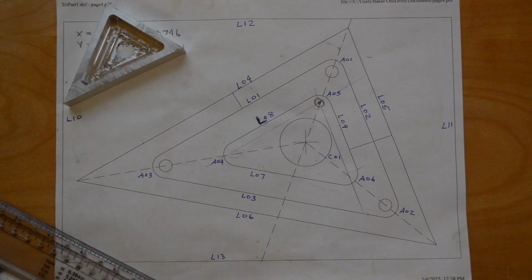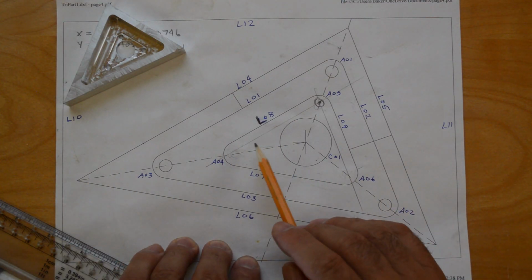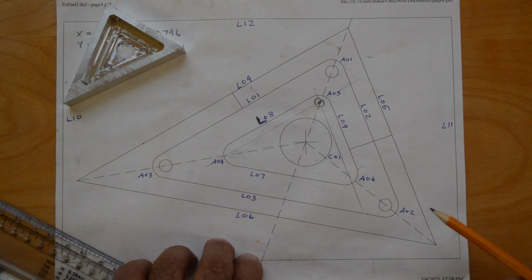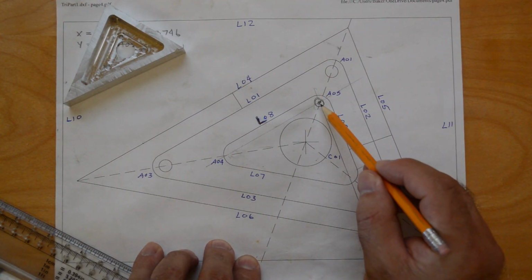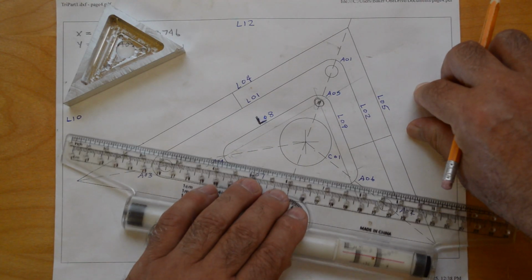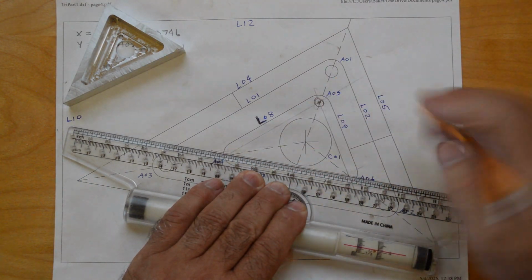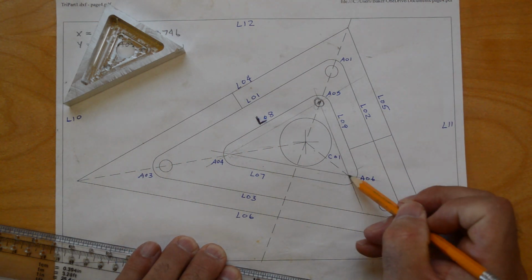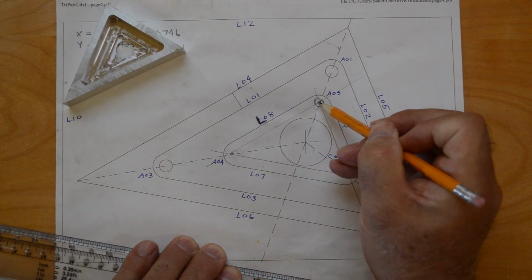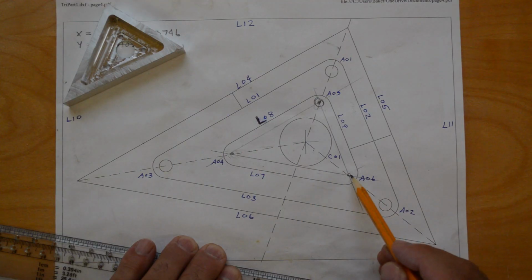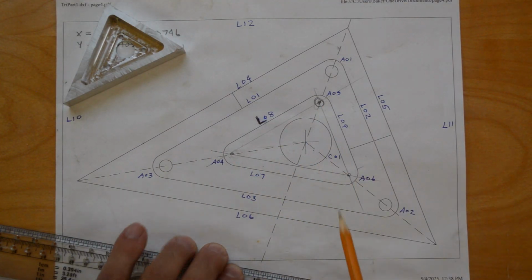So that's what we're going to do on the Cartesian display now. We're going to define these lines, and they are going to become part of our part model. I will be able to use them on radar to navigate to these points and drill these holes. We'll define 3 lines actually, at a 0.125 offset from each one of these walls. So I'll have a point here, a point here, and a point here, and I'll be able to use the radar to navigate to these points, and we can pop these holes in, okay?